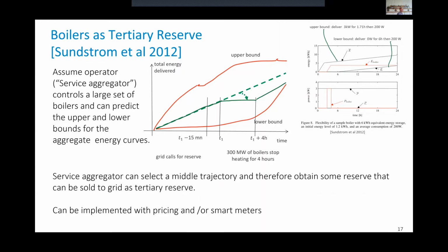So this is deployed. There's another research, described in this paper here, which goes even further and has the idea of using those thermal loads as long-term reserves. The idea here is to play with boilers. Boilers have, in countries like Switzerland, a technology based on highly insulated storage, because this was optimized to grid services where the price is much lower at predefined times of the day, typically at night. So in many houses, the boiler is heated during the night, and then you can take a number of showers during the day. If you exceed that number of showers, you don't have hot water. So you have a storage that can last for hours, in fact, for an entire day. This is how it's been dimensioned.